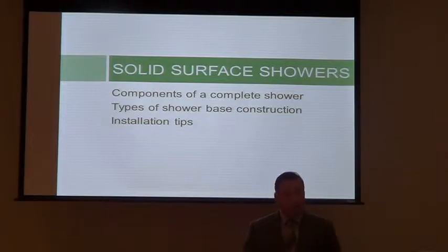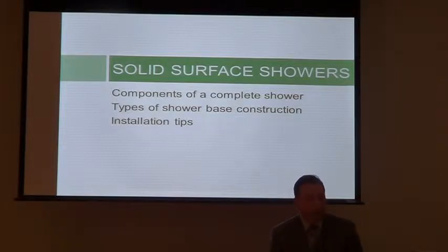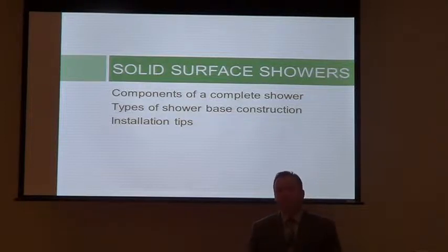There are some manufacturers, of which I work for one, where we actually create a patch kit. It's actually made out of the same ingredients that the product was made out of. And it's mixed up in the field, poured into the void. The advantage to that is it's identical chemistries bonding together. The glue does work, don't get me wrong, but there is an advantage if you can use the actual raw materials. So those are probably the two most common situations.